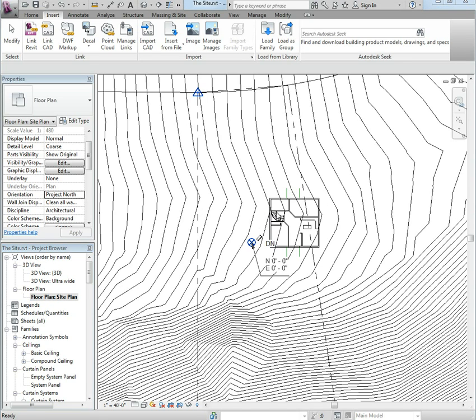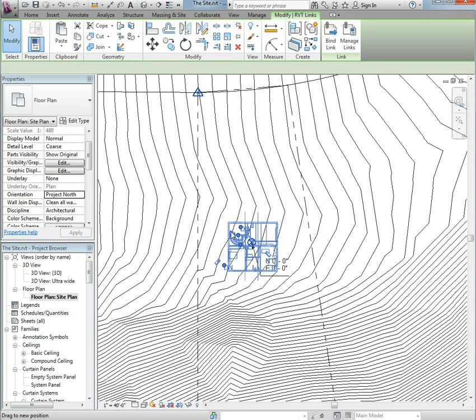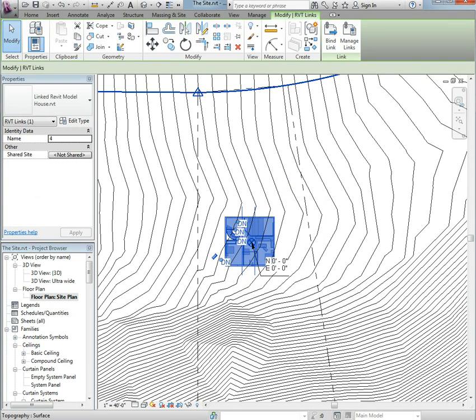What I'm going to do is I'm going to move the building where I really want it to be. And I'm just going to take it and drag it over here. And notice at this moment, if I open the linked file, the survey point inside the house file would be at the startup location in that file, because I never moved it. But also at this moment, the position of the survey point relative to the house is correct in this file. I mean, this is the survey point, there's the house, it's correct relative to this survey point. And we're going to change the fact that it's in the wrong position inside the house file by publishing the coordinate of the survey point to this linked file so that it is correct.